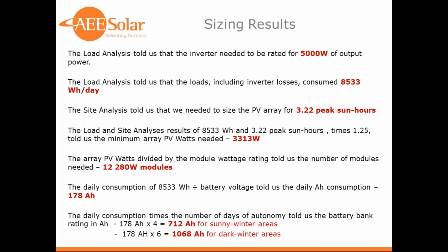So kind of going through some sizing results here, the load analysis told us that the inverter needed to be rated for about 5,000 watts. You could probably use a 4,000 watt inverter if your customers are aware that they can't just turn on every appliance in the house at the same time. So a lot of this may depend on your customer. If they don't even want to think about their energy production, they want it just like downtown, you're going to really want to make sure that you have an inverter that can cover every load that's running.